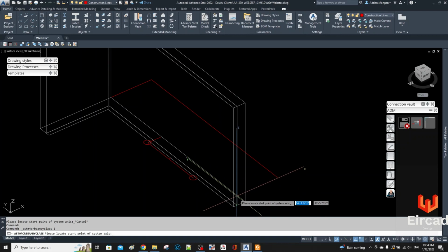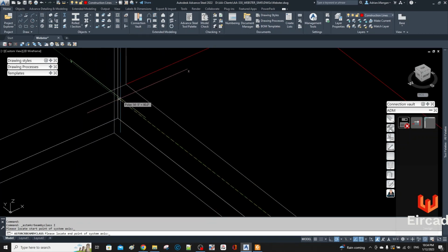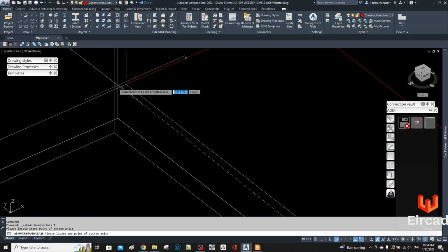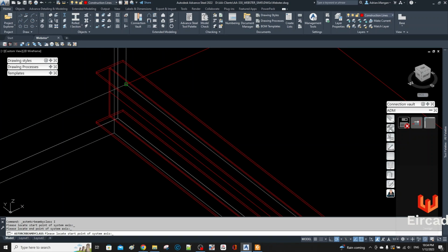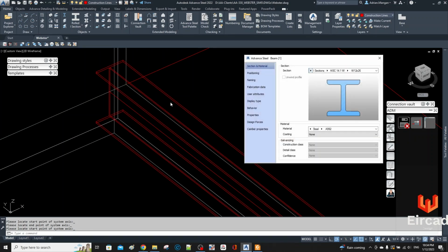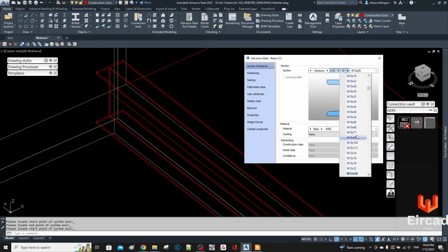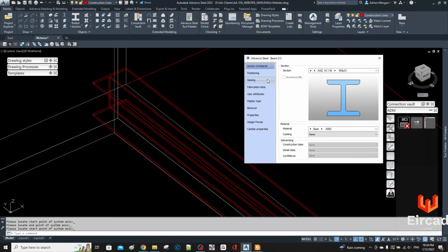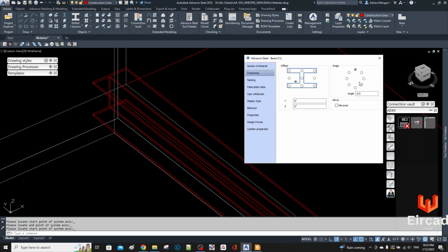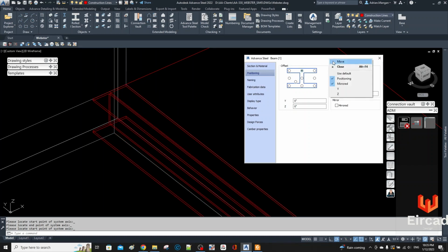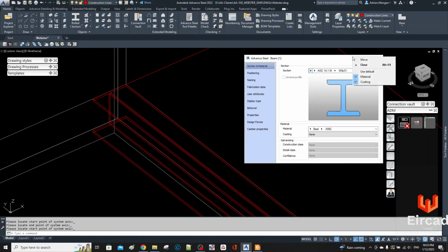Let's go here and do beam from the center, and we'll do it the whole way over. So you can just go here and then let it snap in. Now it's coming on the wrong layer because I have it set to construction layer, which I could have changed. I'm going to go to name and put in beam, then go to top, right click, and I want the model role to come in every time. Go to positioning, I want to position it here, check up top, the position is going to come in the same every time. Material, and yeah, that's good.